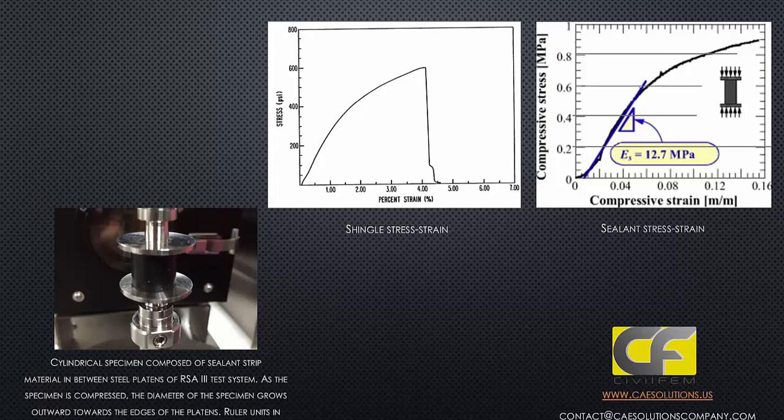The resulting viscoelastic properties were then used to create our finite element analysis models in order to simulate the transient response of a single sealant asphalt shingle structure subjected to uplift pressure loading that they would encounter during maybe a category 4 hurricane for an extended period of time.